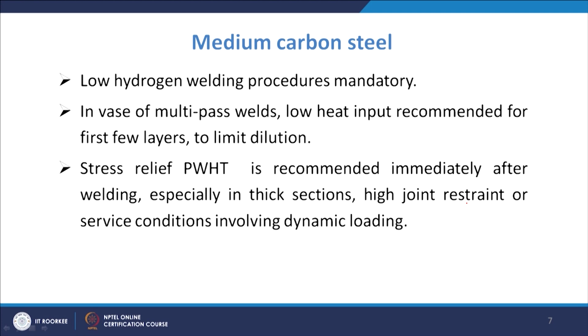In those cases the stress relief post weld heat treatment should be given. And if possible, the welded joint should be heated to the stress relief temperature without immediate cooling to ambient temperature. That is also one of the ways by which you can avoid the formation of cracks.